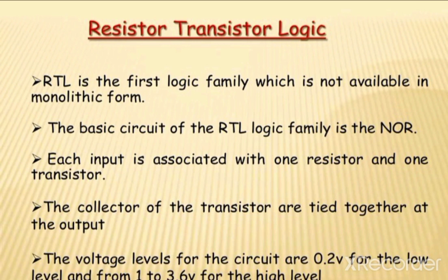The number of input components you are mounting on your digital ICs shows you the fan in. Then power dissipation. This point we have also seen in filters and rectifiers in basic electronics. Power dissipation means that while doing operations, a digital IC produces some amount of heat inside it.